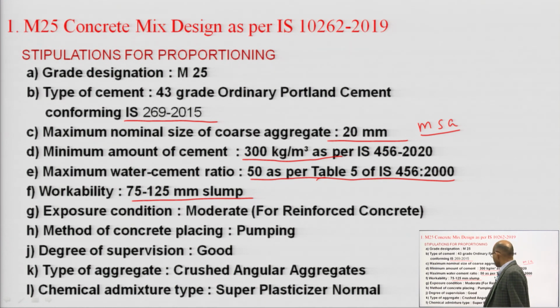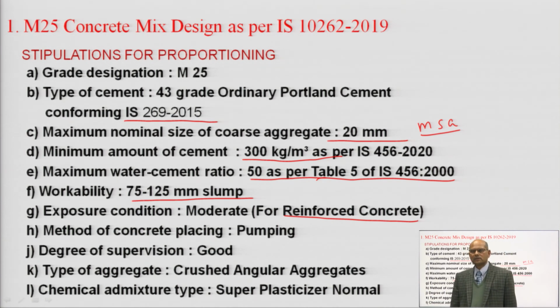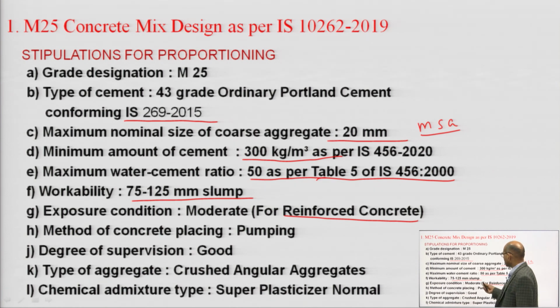Then we have the exposure condition. The exposure condition is moderate. The bracket is given for reinforced concrete. So, for reinforced concrete we have to consider the workability and exposure condition, because you have two conditions: one is reinforced cement concrete, another is plain cement concrete.